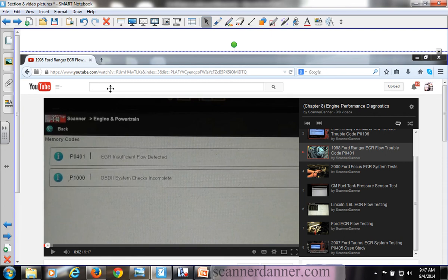This is the most important part. I know you guys are struggling, we want to go to shop, I get it. This is the most important part of the last 2 chapters. How do we apply this stuff in a real world situation? This is what we're doing. This P0401, what do we have? Same kind of code, pretty much. Insufficient flow. Same kind of system. What do?